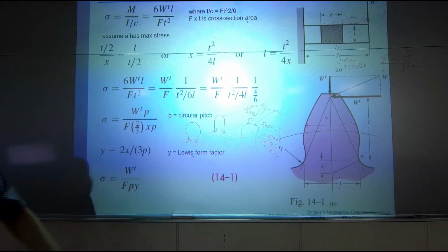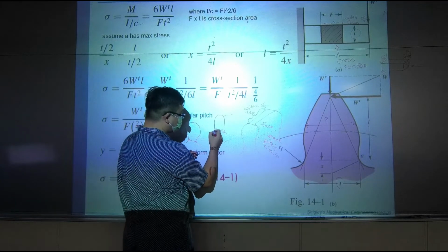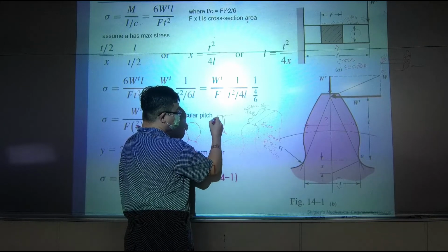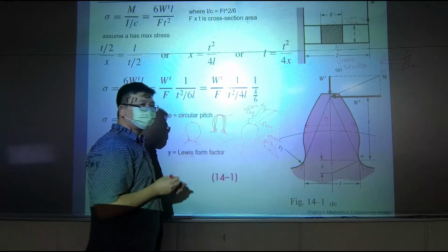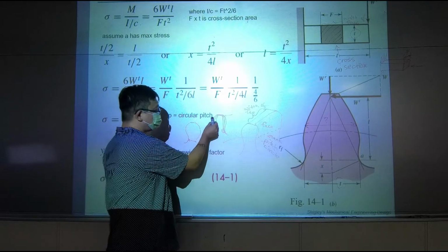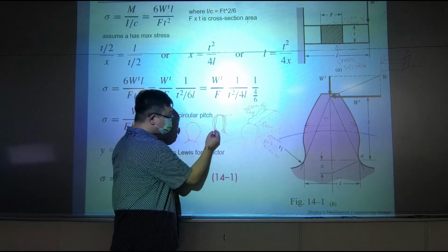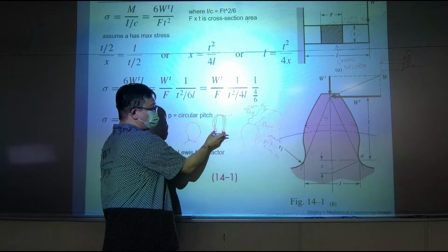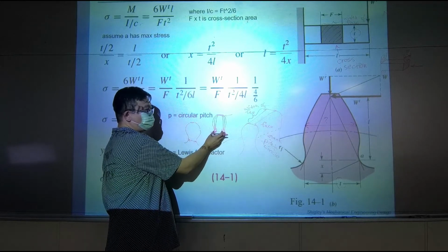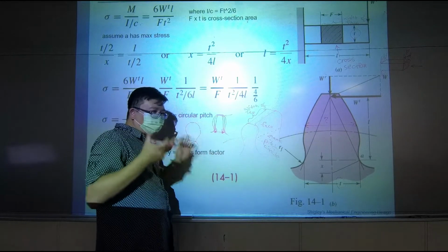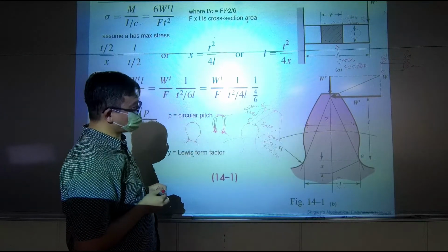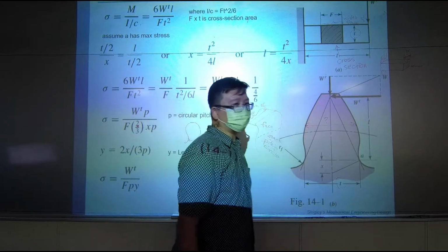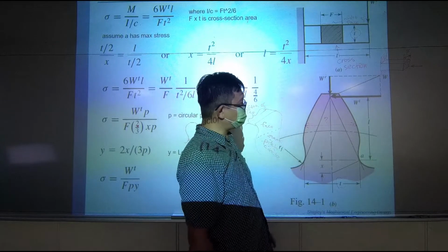So if I have exactly the same geometry but slightly thinner or slightly larger, maybe it doesn't make a difference. The thickness right here doesn't make a difference. The thickness right here matters, because this is how much material you have at the position that really carries the stress. Okay, so I believe those are the 2 reasons why we use this as the key parameter, okay?